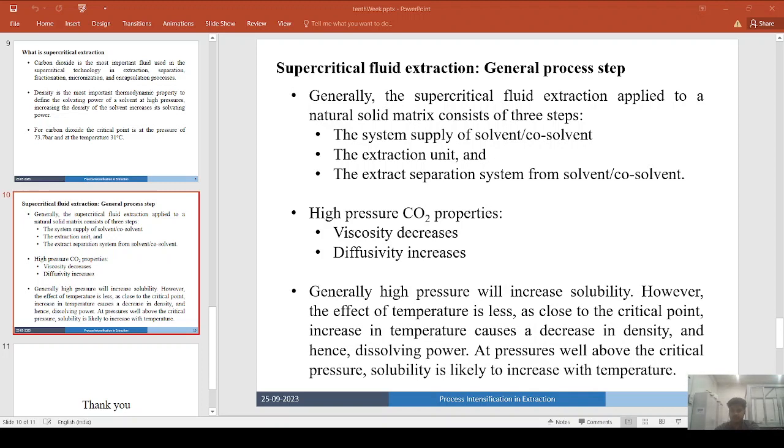So carbon dioxide extraction is basically safer, purer and cleaner. There are a number of advantages to extracting with carbon dioxide, whether subcritically or supercritically. One is that no traces of solvent are left behind, versus other methods of extraction using hydrocarbons. Carbon dioxide is not a volatile solvent, so there is no need for special safety equipment. Finally, carbon dioxide is relatively cheap and 90% of the carbon dioxide used in each extraction can be recovered and recycled.